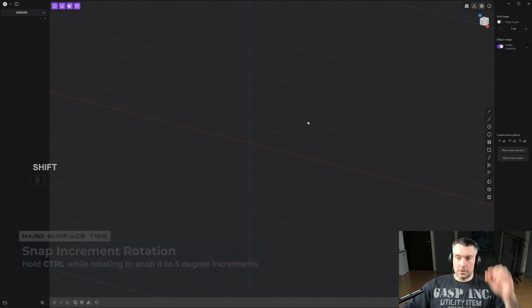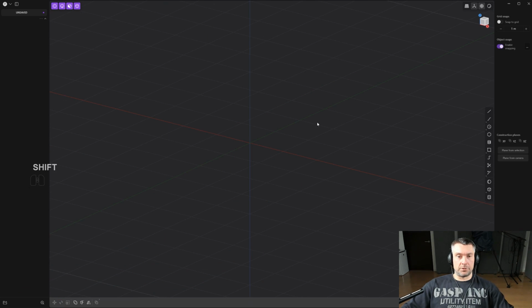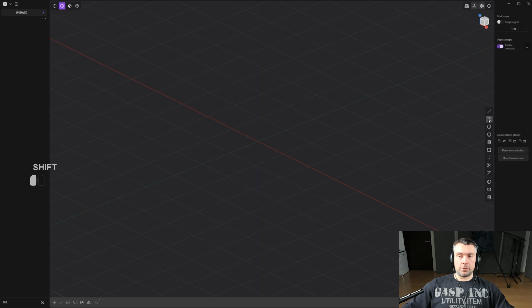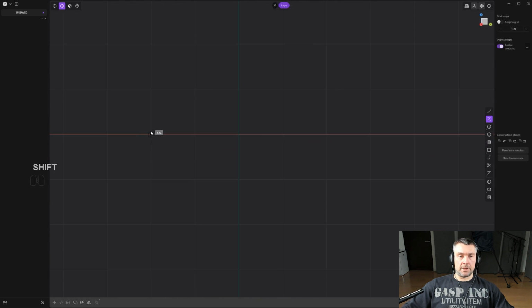All right, cool. Let's talk about some other operations that you may need to know, and it's curves. You're going to be working with curves a lot. So I'm going to show you some very basic lofting, okay? So what I'm going to do is grab a curve. Go here and hold, choose this curve, which is a control point curve. Go to the right view with Alt and middle mouse button, and then simply draw a curve with the left mouse button and right mouse to confirm.